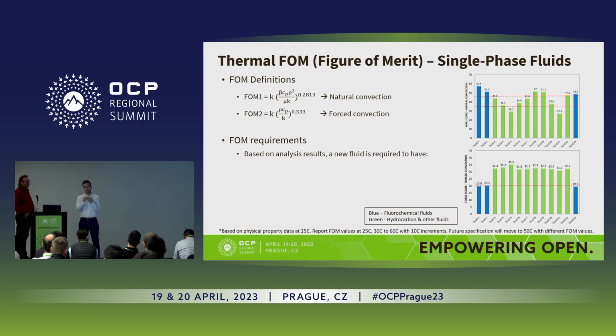So in terms of the first thing, removing heat, we've had this problem for a while now where if you want to try and assess how well a fluid removes heat, you open up a typical product data sheet of a fluid and you'll see a number of properties which affect that, but especially density, viscosity, thermal conductivity, and specific heat. And if you just take any one of those, you can't really come up with that proper assessment of how it removes the heat because it's a combination of those properties.